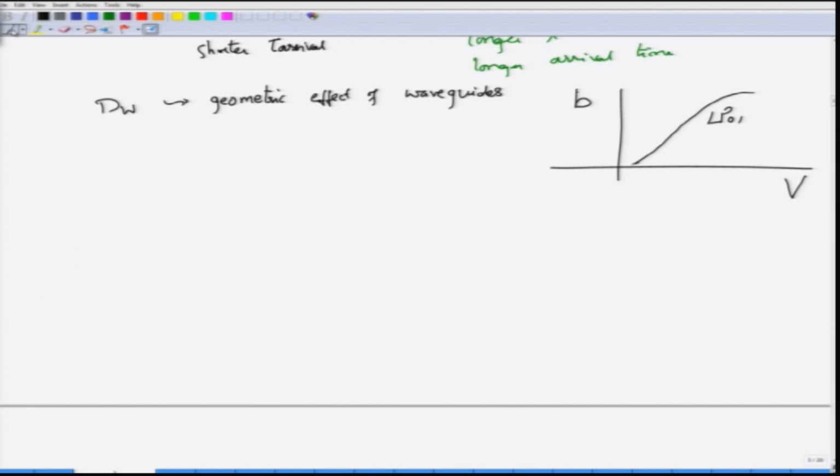Look at this, we have this cutoff value for single mode, around 2.405, and we have mentioned that if you want tighter confinement of the energy inside the core, then the corresponding V number should be very close to 2.4. It has to be as large as possible. Of course it cannot be larger than 2.4, then the fiber would not be single mode, it would become a multi-mode fiber. But larger V means a smaller lambda, and also means tighter confinement.